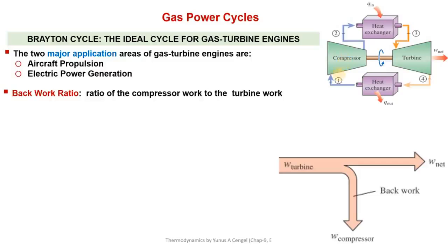In the steam power plant, it was a liquid, and that's why there was a pump. Since a liquid is compressed instead of a gas, the steady flow work is proportional to the specific volume of the working fluid, v times (P2 minus P1). We used this to calculate the pump power because the specific volume was not changing.